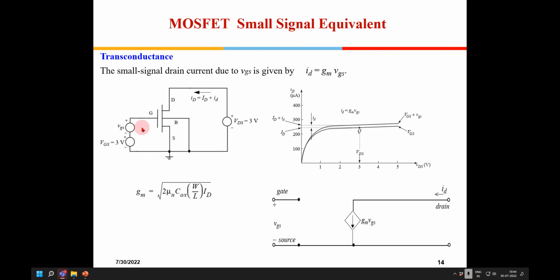No, it's not fixed. Small signals are generally not necessarily tiny; when you are doing power amplification and so on, this can be large also. Is there any constraint on this small vgs? Yes. When we bias these transistors, say in the saturation region, you cannot give a signal so large that it comes out of saturation. In a circuit, then the signal will get distorted.